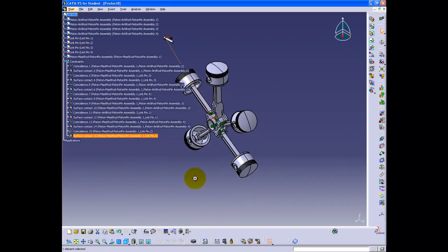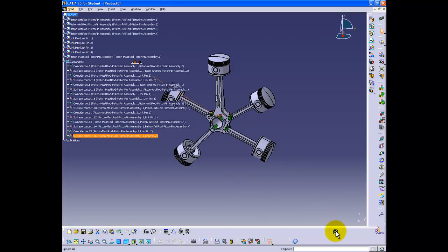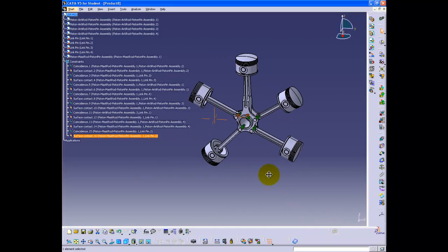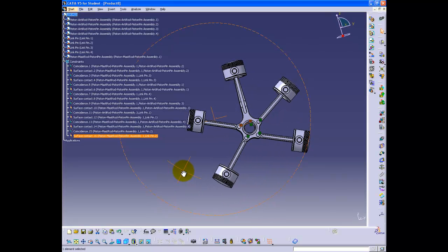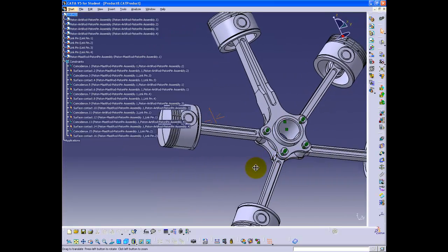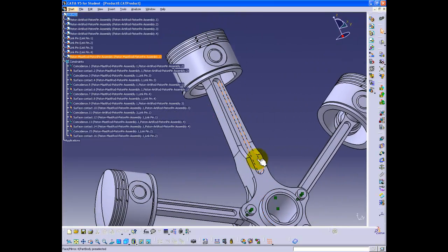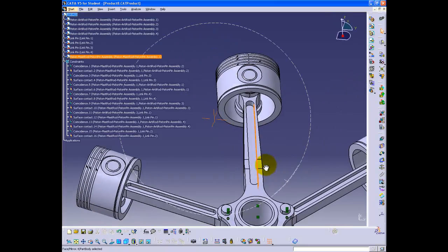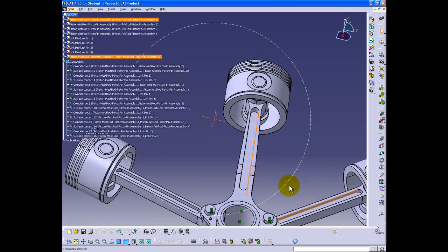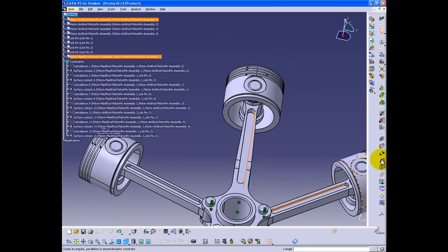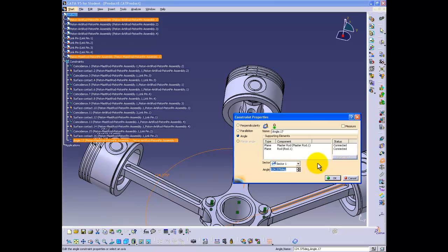Here we see the final general shape is coming along, and we are now moving on to the angular constraints that we mentioned at the beginning of this video section. When choosing the surfaces to constrain, remember to choose them because they are perpendicular to the part shown, and are the inside faces that face each other as shown in the video. Then, once these two faces are chosen, move to the Angular Constraints button and key in the required values.